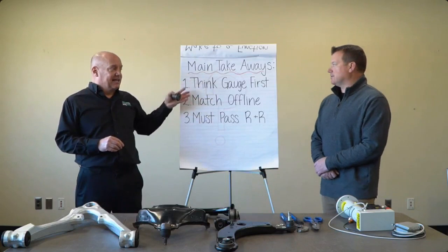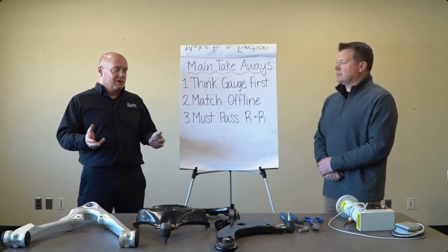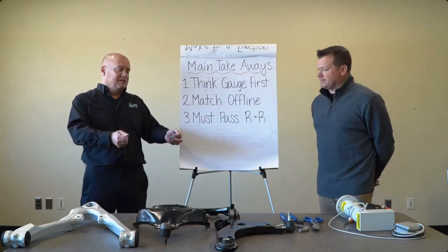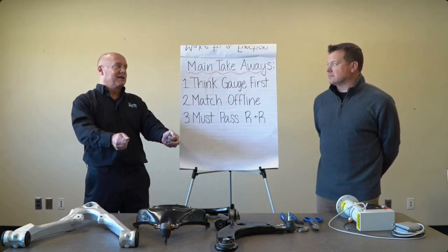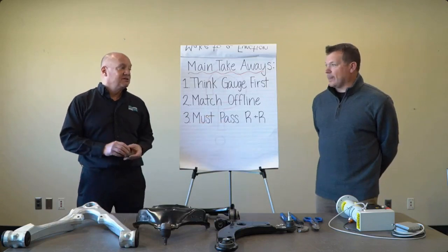The measurement technique, whether it's dimensional or torque or whatever, you have to be able to measure the part. Like if I take a part out of the station, I want to remeasure it, I have to be able to put it back in the station and remeasure it. I mean, that's part of being able to do a gauge R&R. So that's a critical thing also.